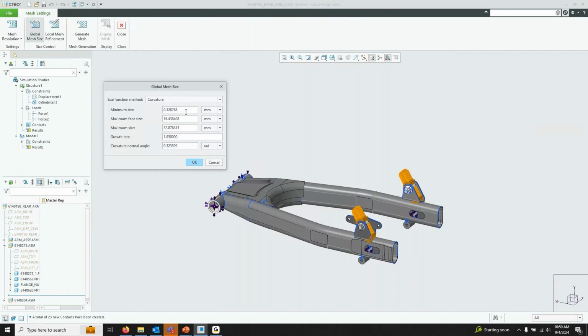I can, of course, further change these if I would like. So I'm going to change the minimum size to 2. I'm going to make that a little bit bigger so we don't get as many really tiny elements. But I'm going to change the maximum sizes of each facet or of the entire elements and make those much smaller. So the idea there is we're going to have a lot of smaller, more regularly sized elements just as a starting place, and we can go from there.